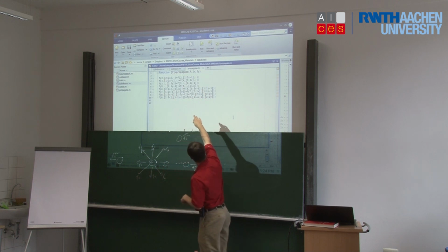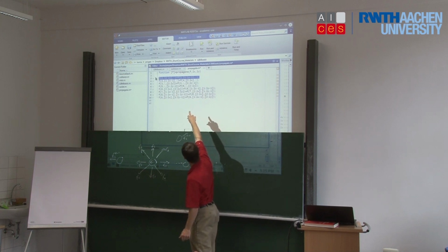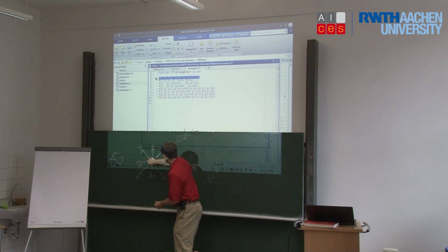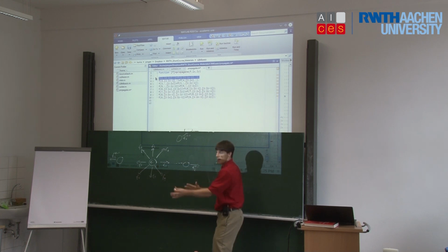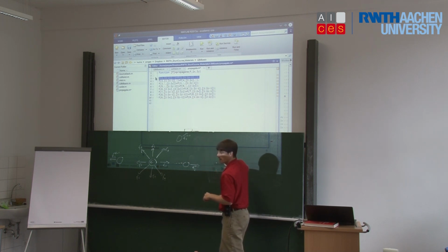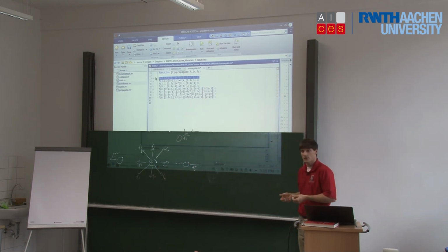And so the way that we can implement this is, if we're looking at this code right here, let's look at the first line. What this does is we just say all F2s, we move them from location 1 to Lx minus 1 into locations 2 to Lx. So we move every F1 one location over to the right. Everywhere in the mesh, all at once. The only thing we don't do is the end one at the end, well, it doesn't go anywhere, it leaves the computational domain. And the beginning one at the inlet, well, there's nothing that comes in, it gets replaced by the inlet condition. Okay.